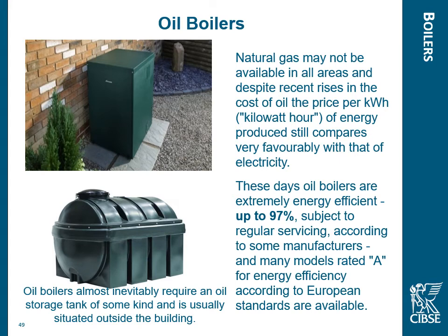Now, oil boilers don't tend to get so many of those nowadays. They were always the number one choice where we didn't have gas. When the oil arrives on site, it's quite efficient. It's just as efficient, if not more efficient, than gas. But when we look at the carbon emissions of oil, we take into consideration the delivery process, and unfortunately, it comes out quite badly in carbon emissions and bad in the building regulations aspects there. Also, oil is quite unpredictable and can be quite expensive at certain times of the year.